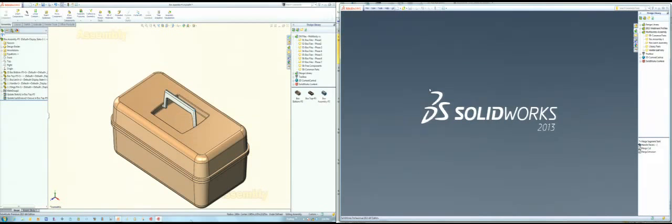Okay? Now the next thing we have to build in here is we have to bring in that latch, and that latch is going to require a boss on the bottom part in order to snap that latch into, and then it's going to require a wedge on the top part so the latch can reach over the top of the wedge and then go over center. Now to do that, I have already brought in the subassembly, and it's out here floating free.